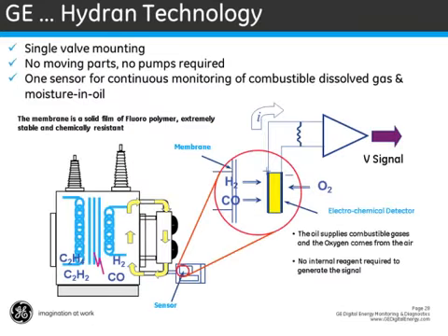So let's take a look now at both technologies. We'll first start with the hydrogen technology. Fuel cells have been on the market for more than 100 years. They come in many varieties and have been proven to work in diverse applications. In 1975, GE took this fuel cell technology and adapted it to enable the detection of dissolved gases in electrical insulating oil. The end result was an online, robust, compact, and self-sufficient device that detected a change in incipient fault gases in a transformer.